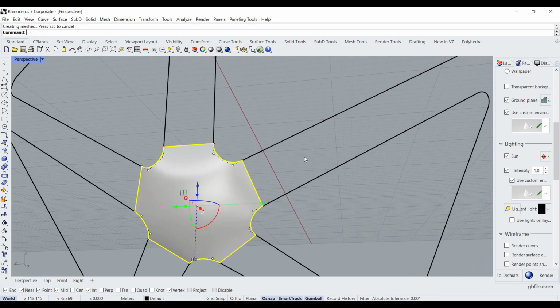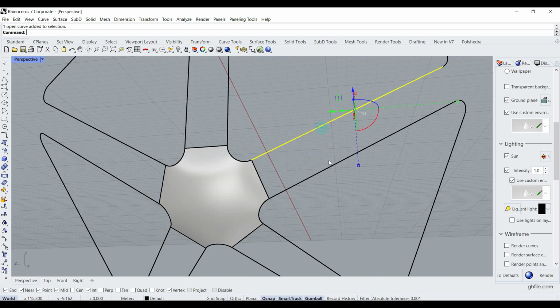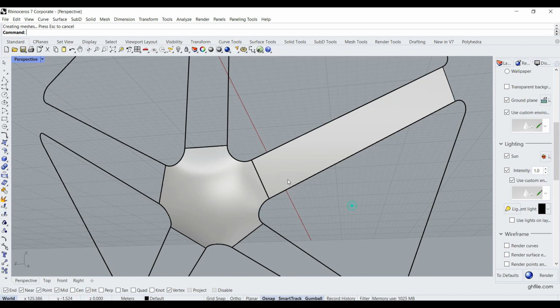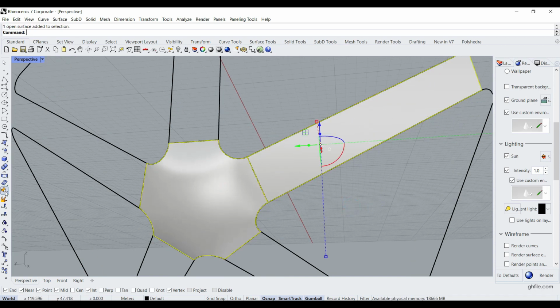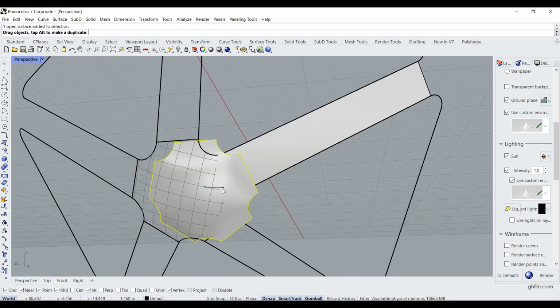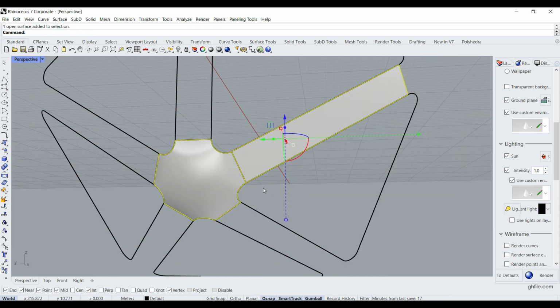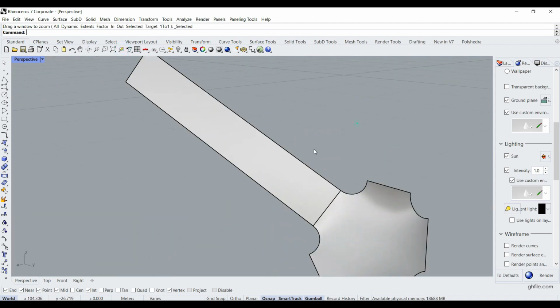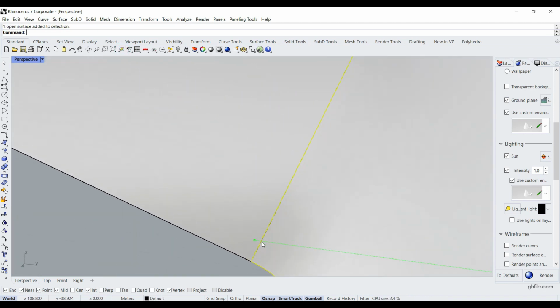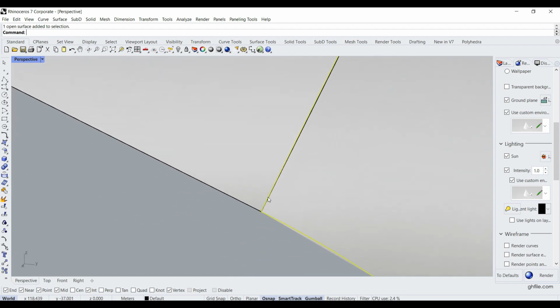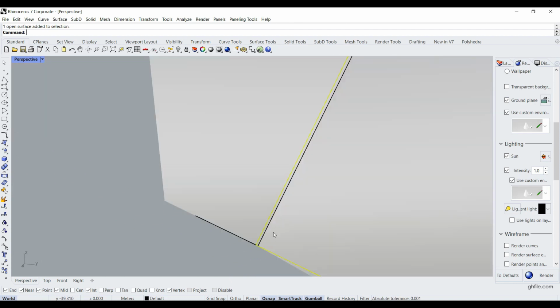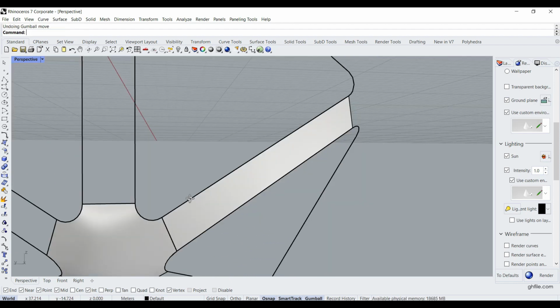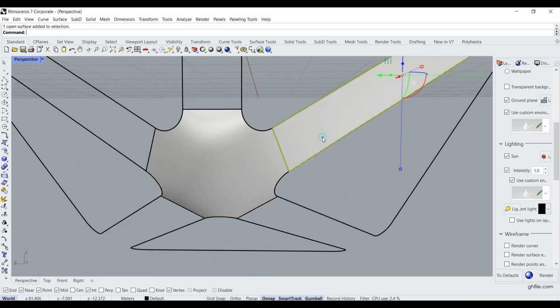The problem we will have here is that if I connect these two lines together as a loft, and for example connect these two surfaces together, as you can see here, they are not going to be connected. And the reason here is because these Nurbs surfaces we have here, they are not really completely connected. As if I zoom in, you can see that this is a little bit outwards from the edges. So we're going to talk about how we can fix this in Grasshopper and finish this tutorial.